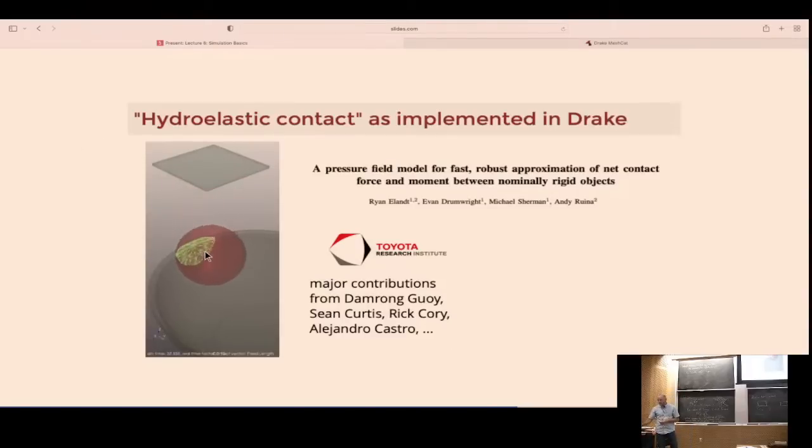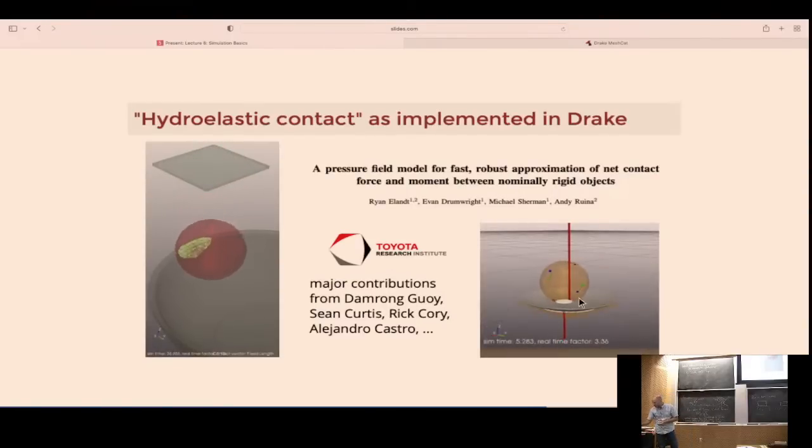It required first a bunch of computational geometry, where you take meshes intersecting with other meshes, and you compute volumetric meshes on the fly of the intersection. And then you try to take a surface inside that mesh, which summarizes the collision boundary, and you take an integral across that surface mesh. And you apply forces in proportion across that whole surface integral. And that has made a huge difference in the way that we do simulation. You get these beautiful simulations that, if you turn on all of the hydroelastic visualization, you'll see the rich contact geometry moving around.